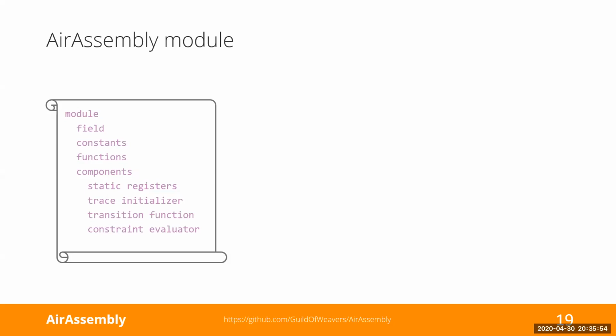If I have some heterogeneity in the computation, because I'm trying to put together two different types of computation, now you have to decide: am I sharing registers? Am I doubling the number of registers and allocating the left for one and the right for the other? How often are they repeating? Is it that for every 5th step of the first computation, I do 1 step of the second type of computation? So these are rather annoying.